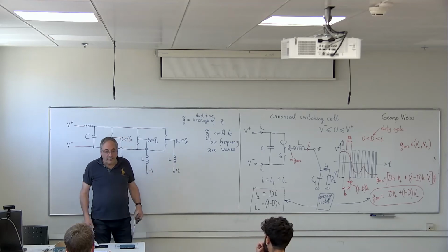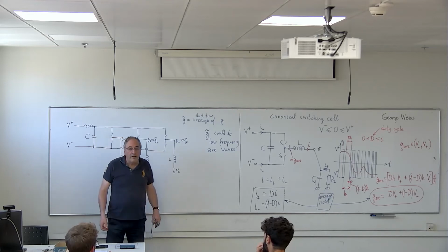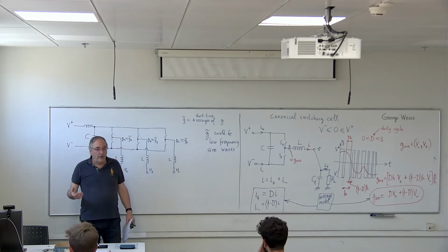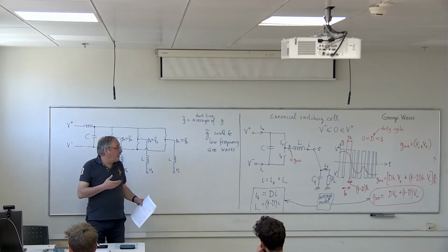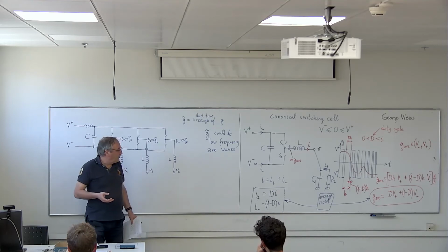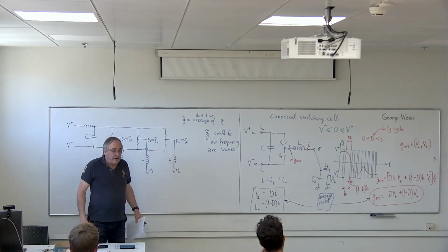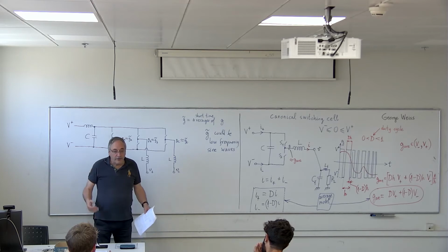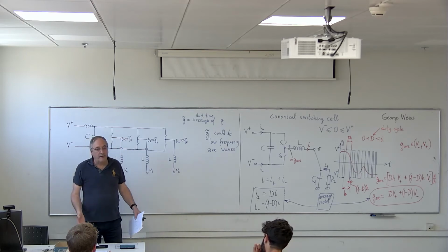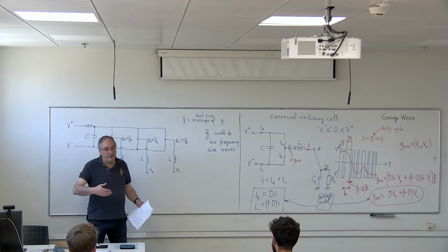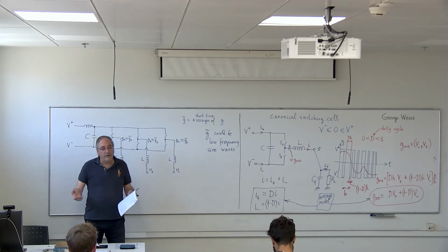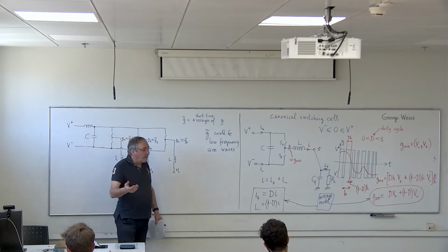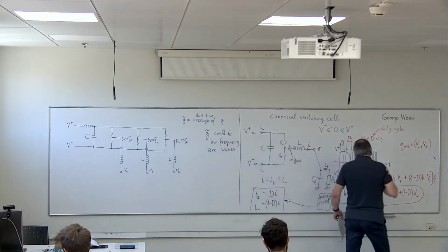Okay, and then once you have decided this switching frequency, then you build your controller in such a way that it executes an algorithm with that frequency. So let's say you have decided that you switch at 10 kilohertz, then you have to have a program which controls this converter, which is executed every 100 microseconds, because that means that the program is executed at a frequency of 10 kilohertz. And at each run of the program, the program will decide new values for the duty cycle.